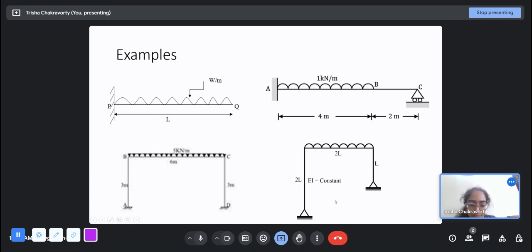And this is another frame with two hinge supports, so there are four reactions and three equations of equilibrium. So this is 1 degree indeterminate. Suppose one reaction of any of these hinges fails. For example, this support fails and this becomes equivalent to a roller. Even then the structure will be determinate because there will still be three reactions. However, if one more support fails, then the structure will collapse.